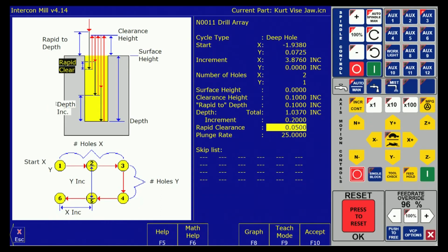So this deep hole tool path is going to drill a depth, retract. Drill a depth, retract. Drill a depth, retract. So what we just populated is what depth it's going to drill before it retracts. Oh, okay. So you're setting your peck depth. Setting my peck depth. Okay, cool. Groovy. All right, here's our rapid 2.